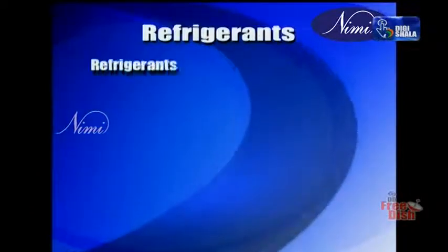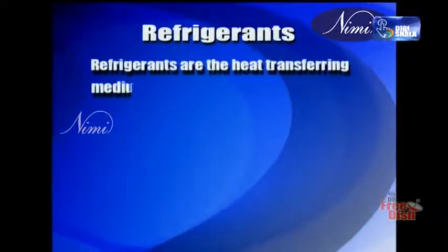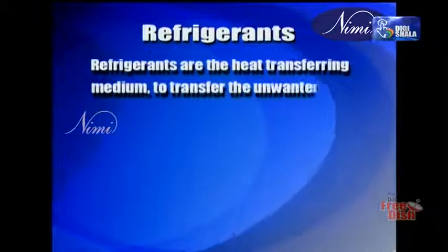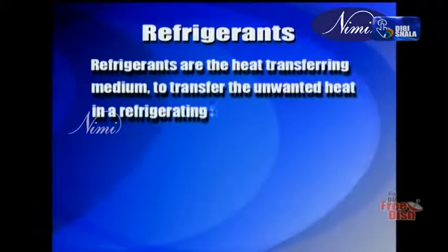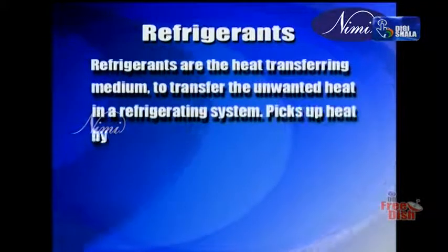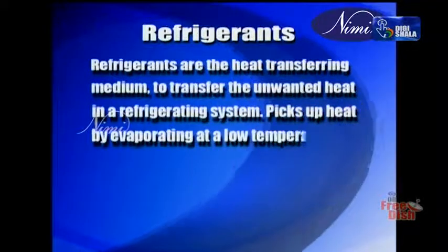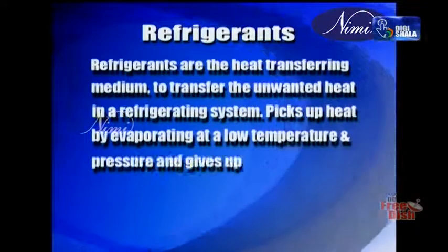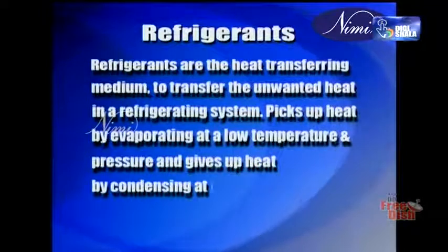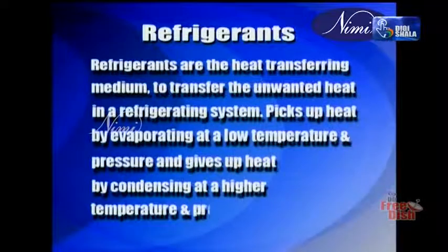Refrigerants. Refrigerants are the heat transferring medium to transfer the unwanted heat in a refrigerating system. A refrigerant picks up heat by evaporating at a low temperature and pressure and gives up heat by condensing at a higher temperature and pressure.